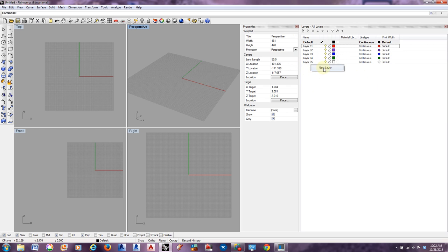You can also create a new layer, and then this check button, if you double click on any one of these, is basically saying that's the layer that I'm drawing on at a particular moment. So if you set these up beforehand and you want to draw on a specific layer, that's how you change your layer to be drawing on that layer.